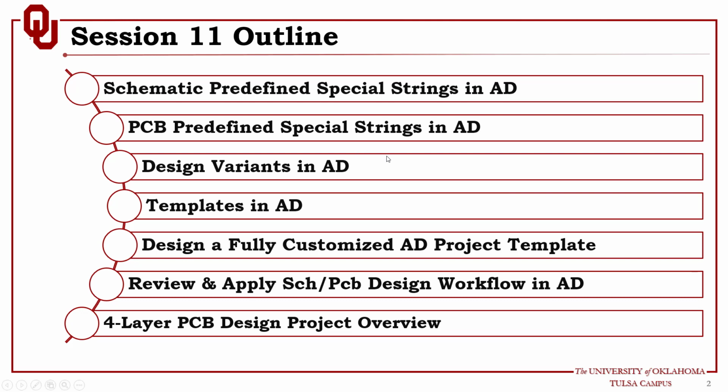So we'll take a look at schematic predefined special strings in Altium Designer and the PCB predefined special strings as well. Then we will talk about the design variants and templates, and we will try to look at what is the best way to design a customizable template for a project that includes customizable schematic sheets and PCB layout as well.